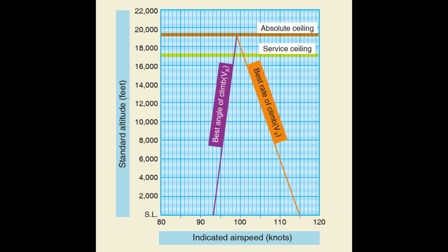In many airplanes, as power is increased, an increase in slipstream over the horizontal stabilizer causes the airplane's pitch attitude to increase more than desired. The pilot should be prepared for slipstream effects but also for the effect of changing airspeed and changes in lift. The pilot should be prepared to use the required flight control pressures to achieve the desired pitch attitude.